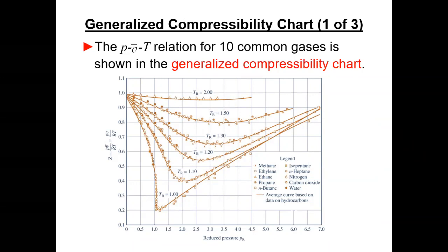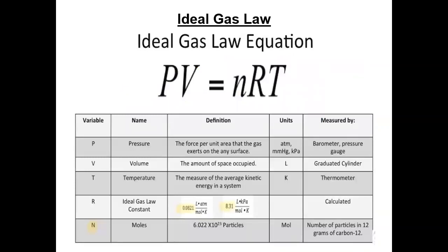And so you see that Z, it's P. Now, this nomenclature is out of your textbook. So Z is equal to pressure times the molar specific volume divided by the R bar, which is the universal gas constant, times temperature. Well, and look at Z. Well, okay, so up here, what is Z? Well, it doesn't show up, so it better be 1, right? So up here, Z is 1.